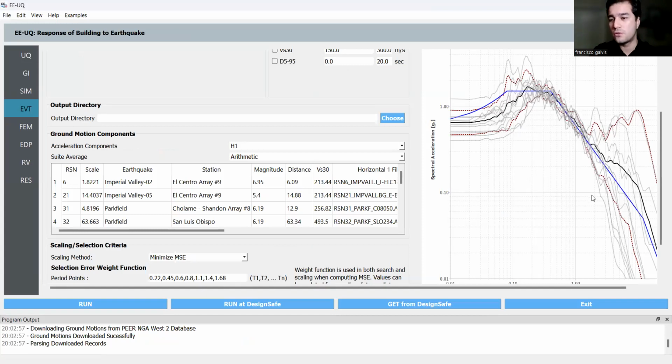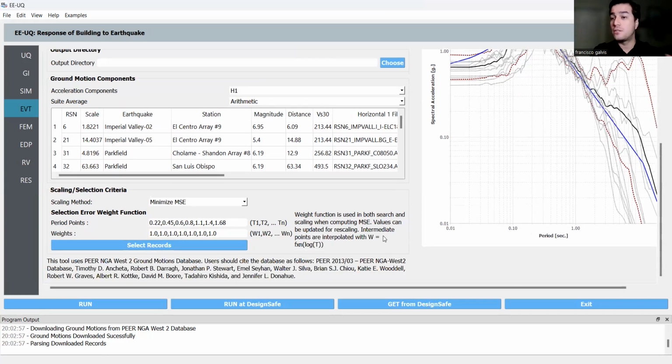to select ground motions. So here you can see on this log plot how, in the region around the 1.12 seconds, we get ground motions that are pretty similar to the target, which is this blue spectra, and each of the gray ones corresponds to each of the ground motions that was selected and scaled, basically multiplied by a scalar to get it closer to that target.